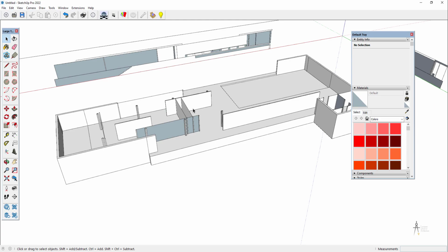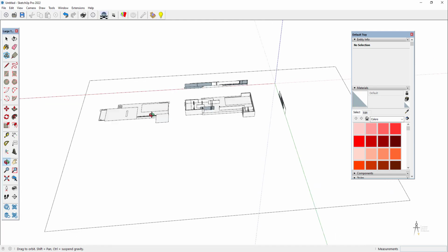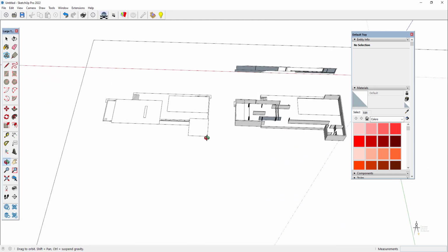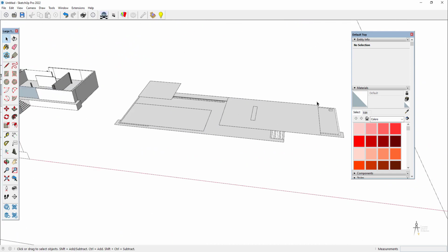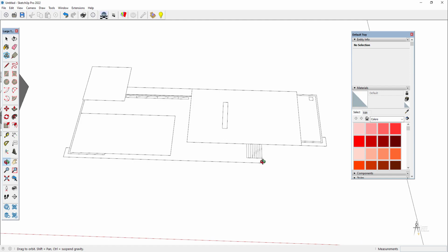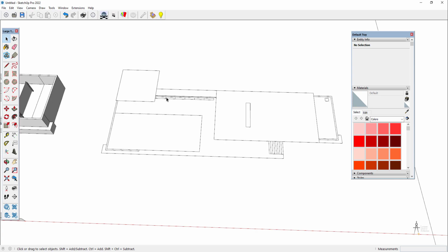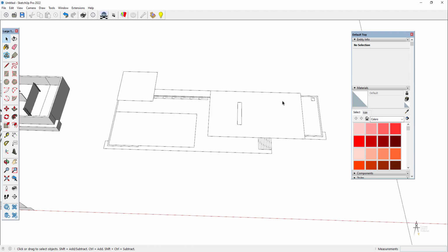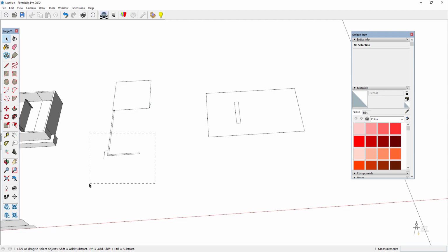Okay, so now that we have our pillars created, it's time to finish off with the roof. If you check out the roof, you will realize that there are a lot of projected lines, and well, you could have sorted this out on AutoCAD, but you can do it now. All of these elements are projections, and we don't want to extrude or create models out of this or anything. So what we're going to do is to erase them here. Again, you could have done it in AutoCAD. So I'm going to get rid of this.